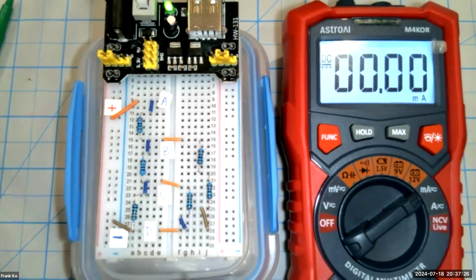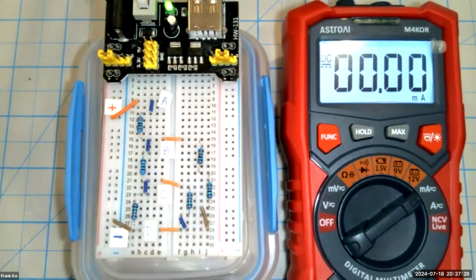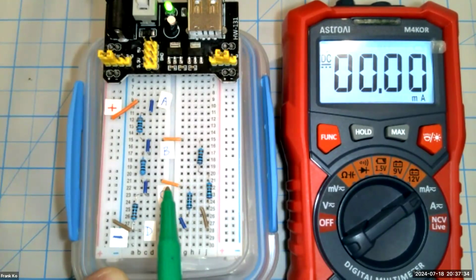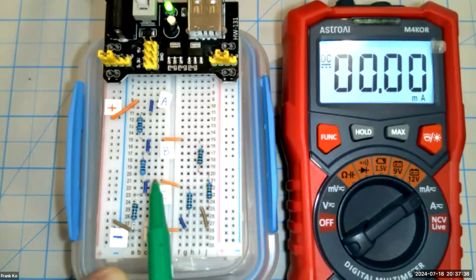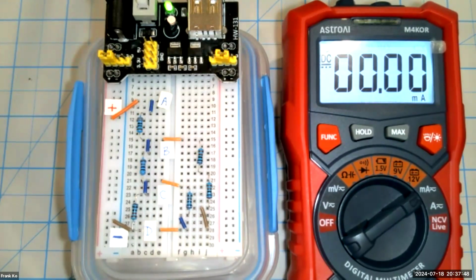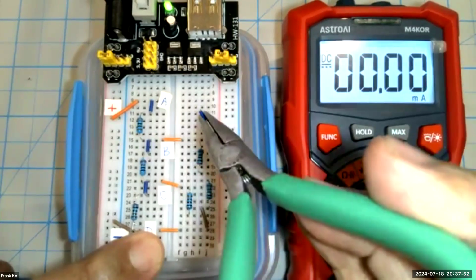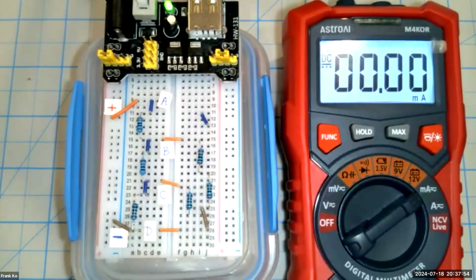So the very first current we're going to measure will be the current through R4. We require 2 volts, 1 milliamp. So the way this is structured, it's flowing 2 volts at point C across the resistor to ground. So if I yank this blue jumper, that will create an open at the bottom of my R4 resistor. Watch this carefully. Yank the R4 jumper. I'm just going to park it temporarily someplace.